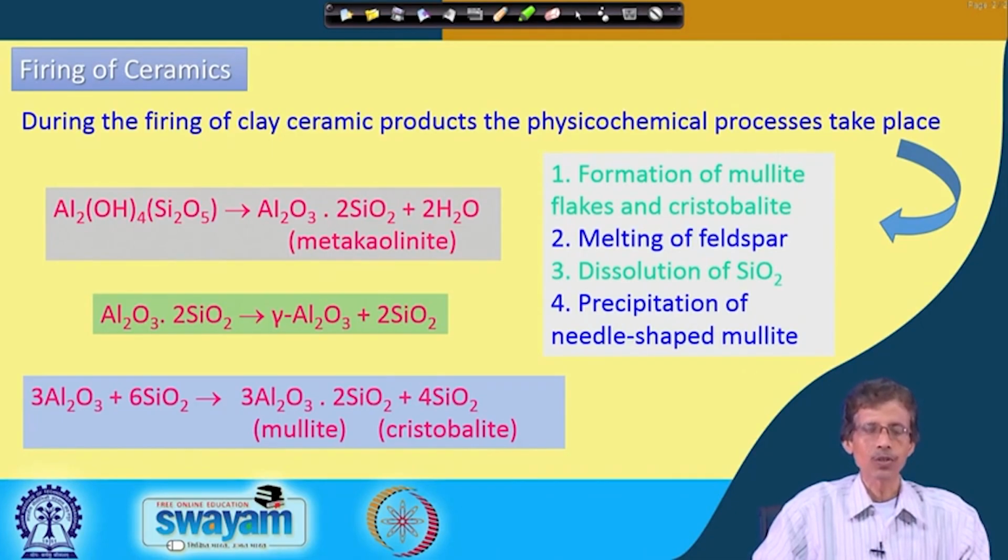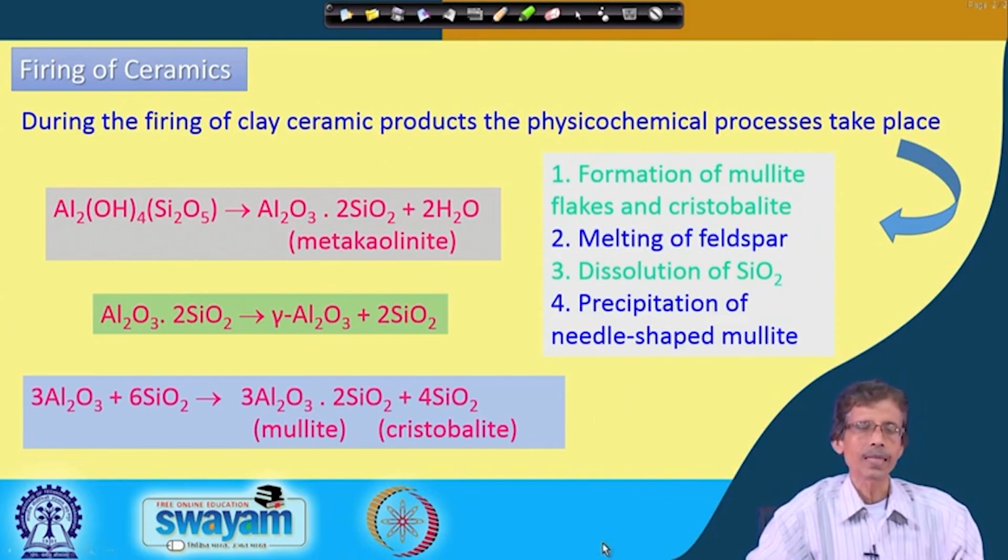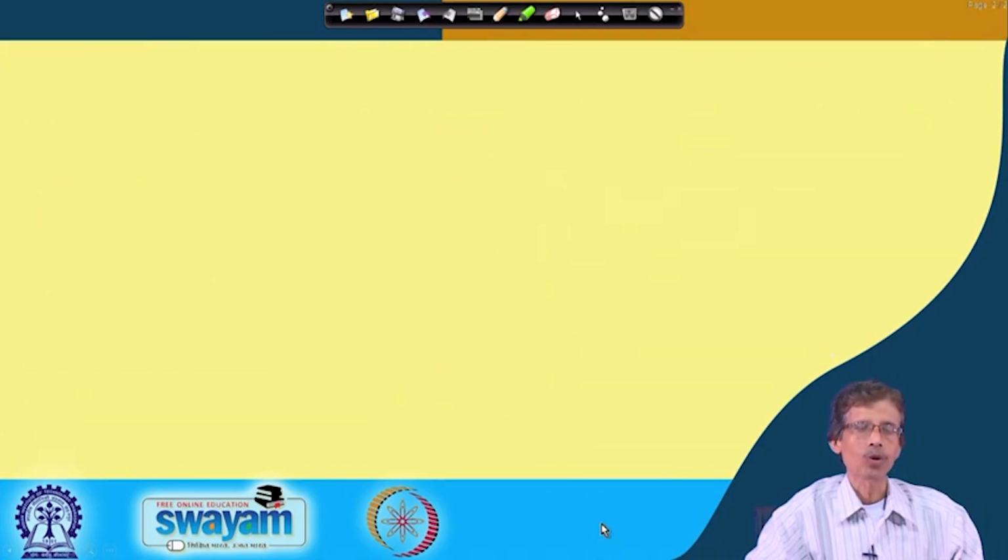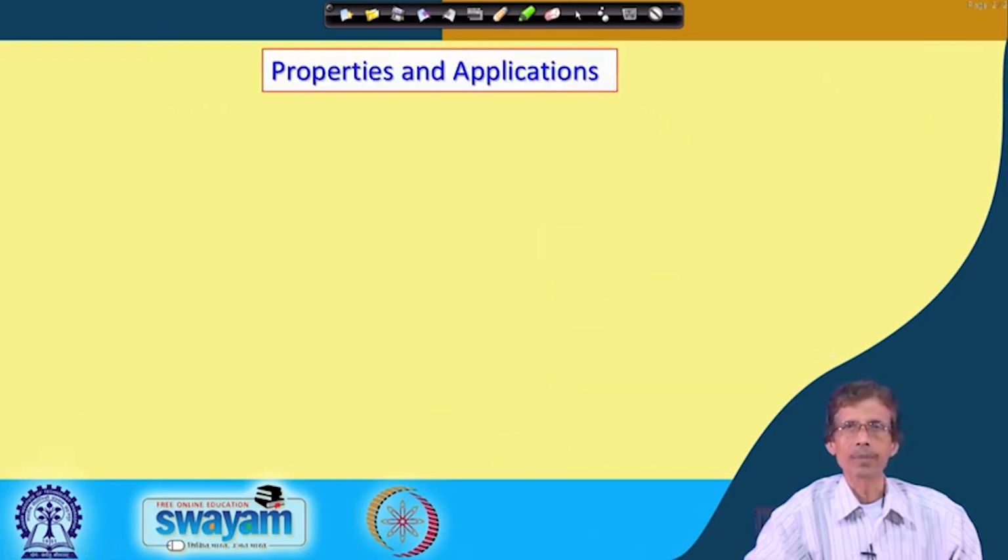One phase is your mullite phase, which is Al2O3·SiO2 with a 3:2 composition. Another is simply the cristobalite, which is typically a silica variety. So, these will all be there in the solid state material, and we are getting towards that ceramic formation out of this chemical reaction at high temperature.